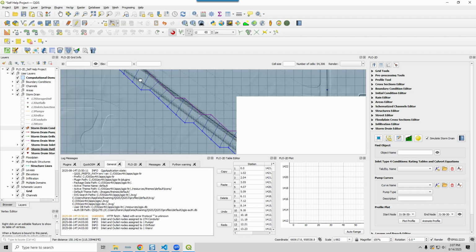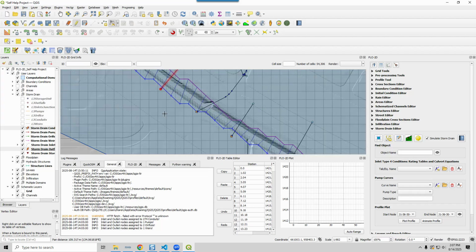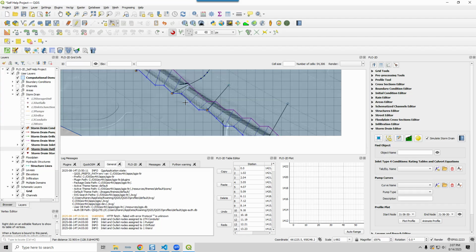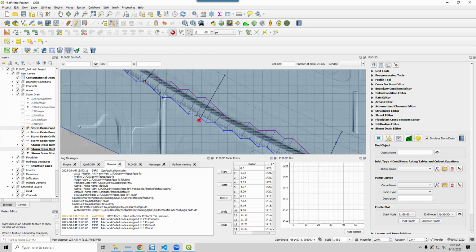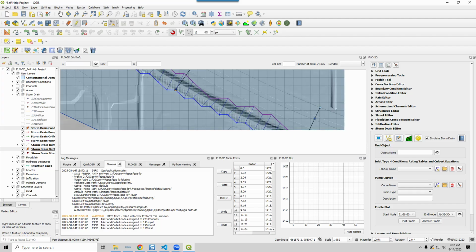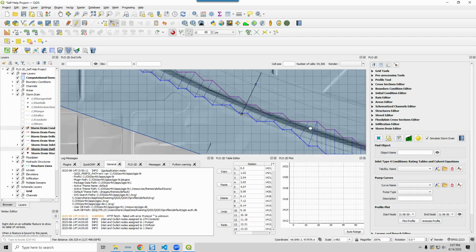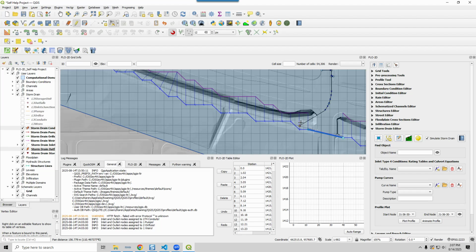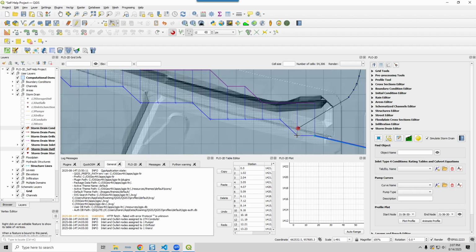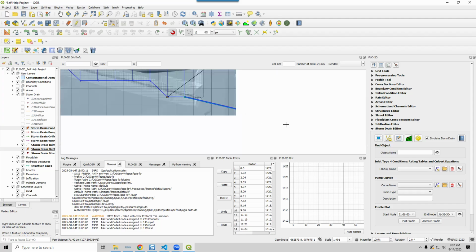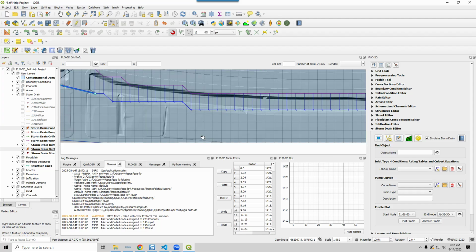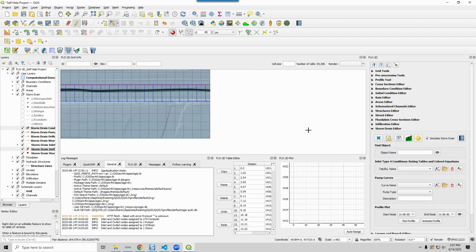I think there's a few more that are also wrong. That one's okay, that one's okay, this one's no good. Got to move that one. Okay, and that one needs to move. Okay, all good. See how that snapping rectangle or snapping is applied. That one's okay, but it's right on the edge, so we can just move it if we want. It won't really matter. It doesn't have to be directly on that center node. It just needs to be inside that grid element.